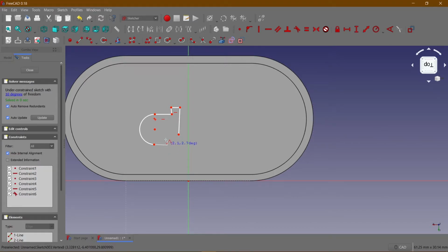So then I need a line again. So I'm going to click on M again until I get to line. Okay, here I am. And then I complete this sketch. At any point of this, make sure that you see the red node change to a yellow color, meaning that there's a coincident at that point. Then you select it, and that is it.